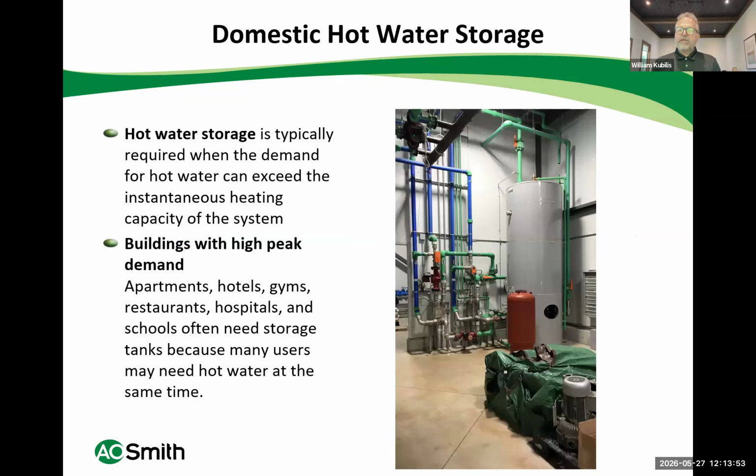Just to talk about storage for a second. The advantage of having storage is it does take a little bit of pressure off of us as designers because I have a little bit of reserve and a buffer, if I wanted to call it, of hot water stored in the bank so that I can deal with short, instantaneous, high demands. So, it's typically required when the demand for hot water can exceed the instantaneous heating ability of the equipment.